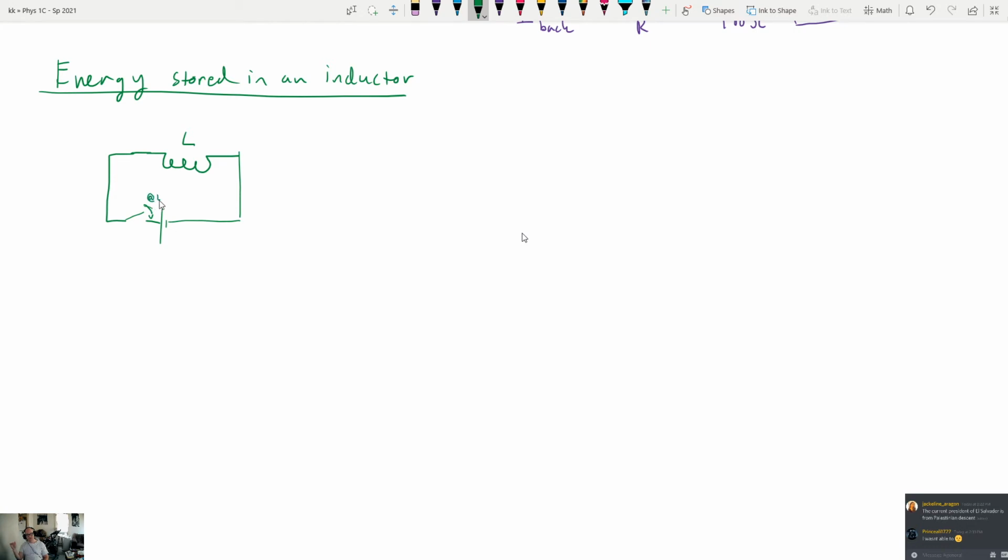DC circuits. And what we're going to find is that inductors and capacitors both become much more interesting when we talk about alternating current circuits. When the current flows left and right, back and forth, the inductor is going to be able to do what it does, which is resist changes in current constantly. And the capacitor is going to be able to do what it does, which is charge and discharge constantly. So the fact that it creates a short circuit doesn't really mean anything at that point.